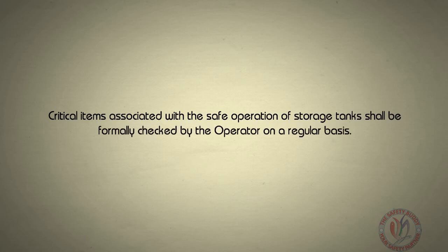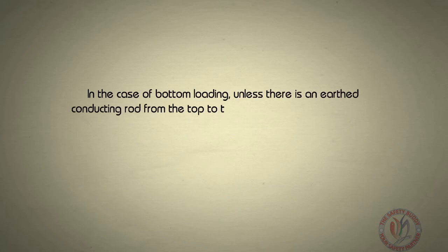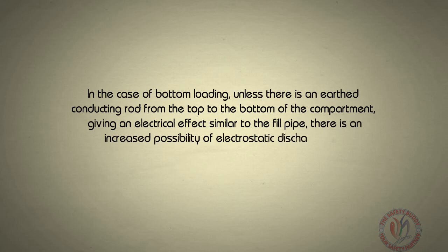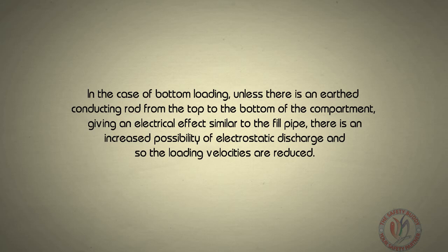In the case of bottom loading, unless there is an earthed conducting rod from the top to the bottom of the compartment, giving an electrical effect similar to the fill pipe, there is an increased possibility of electrostatic discharge, and so the loading velocities are reduced.